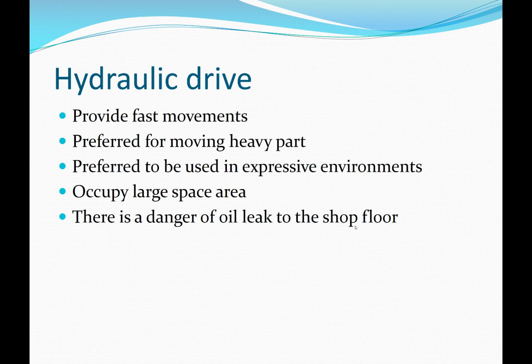And there is the danger of oil leaking onto the shop floor. I worked at a company where we used a lot of hydraulic motors and a lot of pneumatic motors running machinery in the factory. A lot of times we'd get hydraulic leaks, and sometimes they're quite hazardous. I've seen people get hydraulic oil spraying in their eyes at high temperature. As far as I know, nobody on my shift ever lost their sight because of it, but they spent some time at the eye wash area.